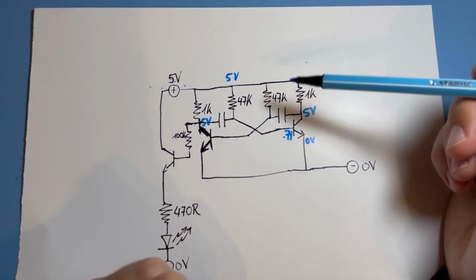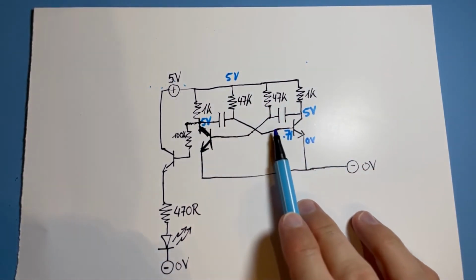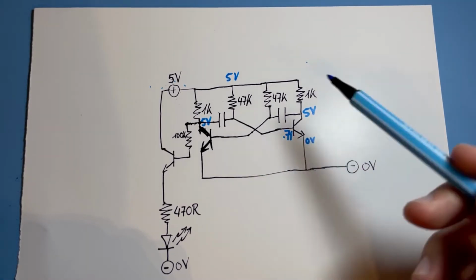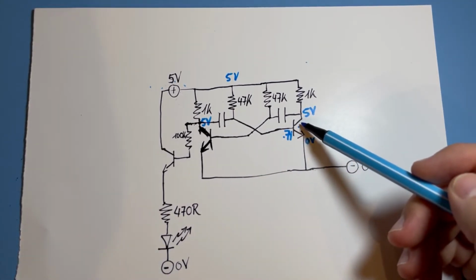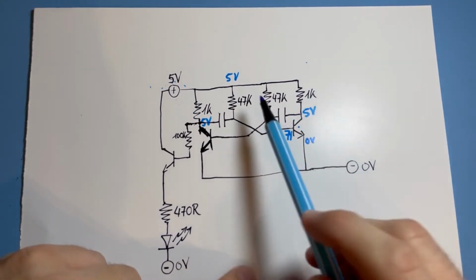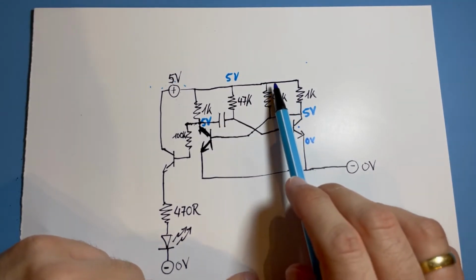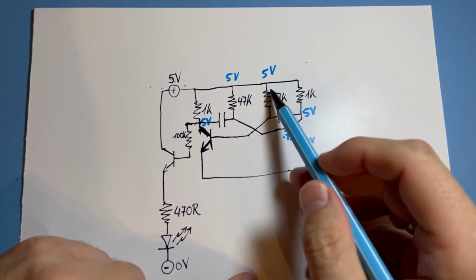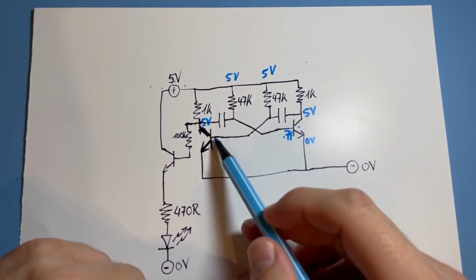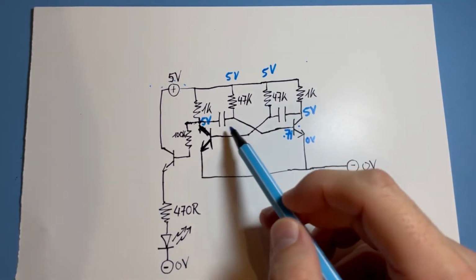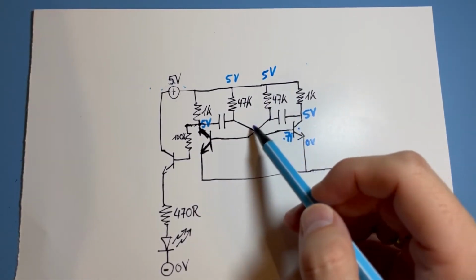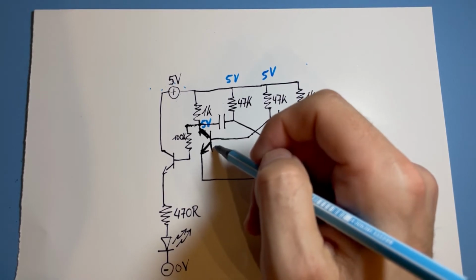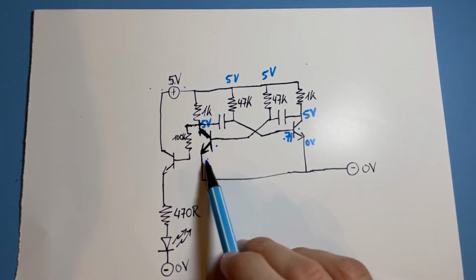And so if this happens, then this transistor is conducting. And now you ask me, okay, but what about the other 47K resistor? We also could say, okay, here is 5 volt, and there's also a path here to ground, and there could be also current flowing through here, and there also could be 0.7 volt here and 0 volt here.